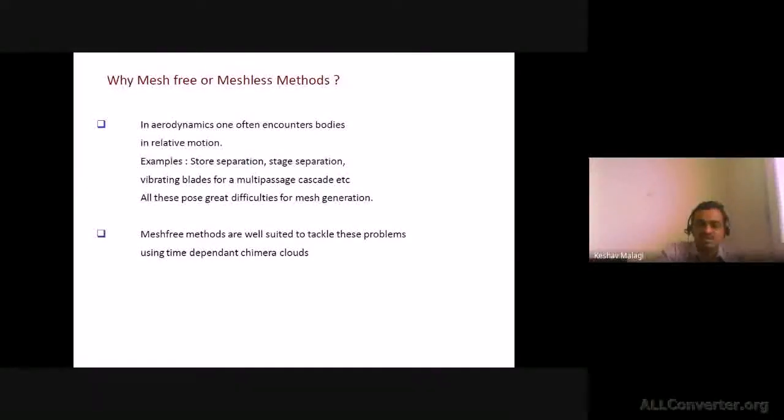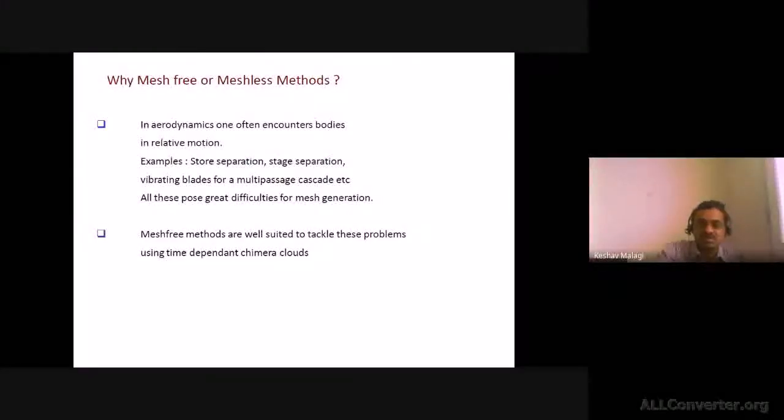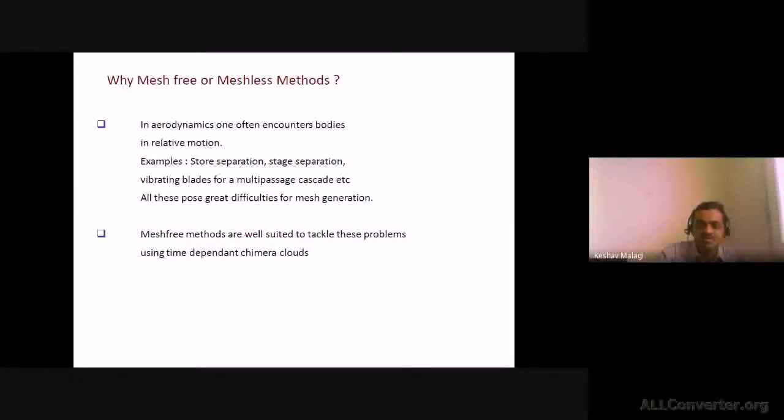Once there are problems with stage separation, vibrating blades, all these where there are moving boundaries, it is very easy to manage with these meshless methods. And also when there are time-dependent chimera clouds, that is, as the body moves you will have these overlapping meshes, as I said about the store separation, aircraft plus store, that is one example of a time-dependent chimera cloud. So you can see that it is pretty easy to handle with this.